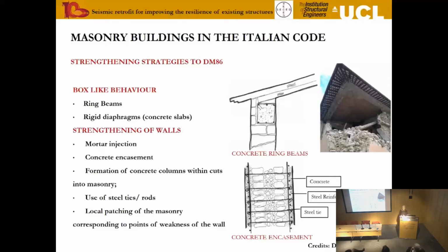The approach there, from a structural point of view, given the level of education of the average engineer at the time, was the ability to design frames, whether concrete or steel frame, better if steel frame, and better if with what we call admissible stresses, which I don't think the younger ones of you even know what it is, i.e. just a safety margin, and we consider that the behavior is elastic.